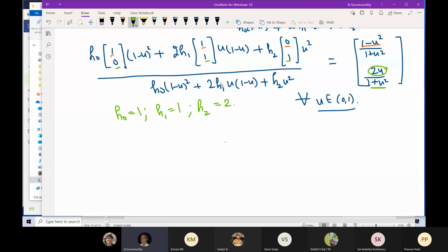What I want to do first is to highlight one thing, which is a shortcut, because we don't have the time to derive this. Remember, I said that for the Bezier curve, P of u equals the sum of pi bi,n of u. I had shown you by a quick step that the sum of the basis functions is equal to 1.